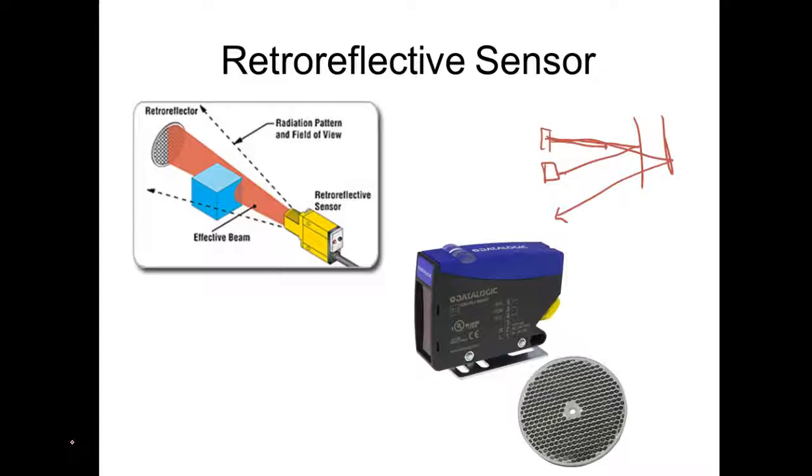Well, it all depends on what type of sensor you have, whether you're using regular light or laser for your light source. Laser has the problem we have with just about any light. If it's not a pure light, what happens as it travels over a distance? It diffuses. So what does it do? It spreads out. So that's one advantage laser has. Laser is light at one frequency, so it maintains and goes a longer distance before it diffuses. It still diffuses, but less.